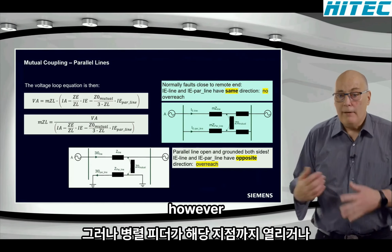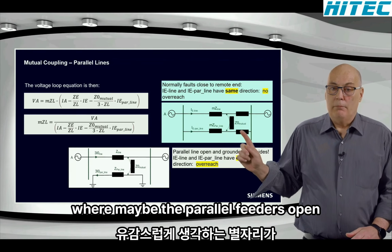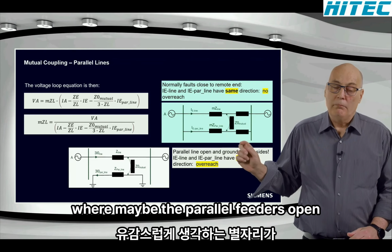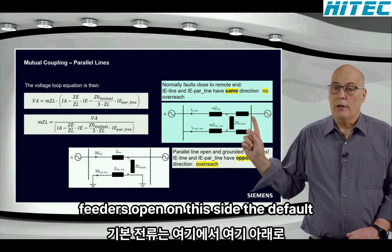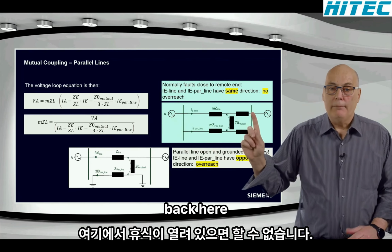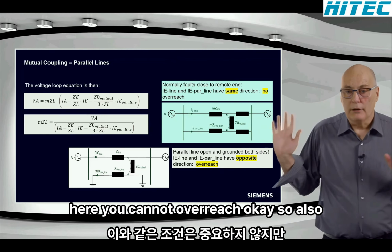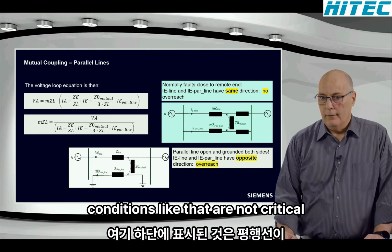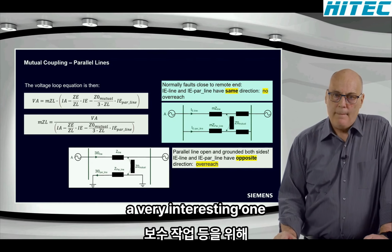However, there can be constellations where the protective feeder is open on this side and the fault current will come from here, down here, and around the loop back here. Not so serious, but if the breaker is open here, you cannot overreach. So conditions like that are not critical. But the one shown at the bottom here is a very interesting one.